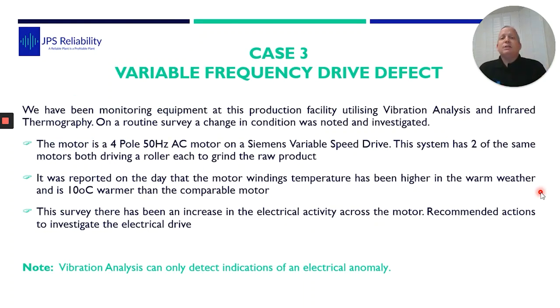A bit about the history. This is a routine site we go to regularly. Electrical thermal imaging, a bit of mechanical thermal, but it's mainly vibration analysis on the mechanical plant. On the routine survey, we noticed a change in the vibration pattern, not necessarily amplitude, but there's a distinct change in the pattern. So we used thermography to check out the motor, and usually there is a temperature difference as the seasons change, but on this day we could actually see a 10 degrees difference in the motor stators.